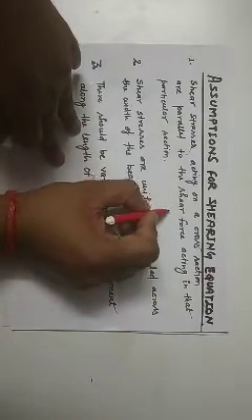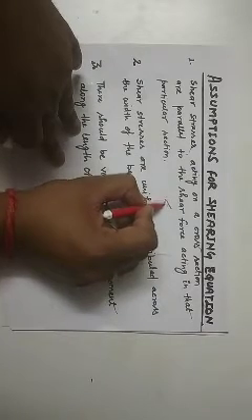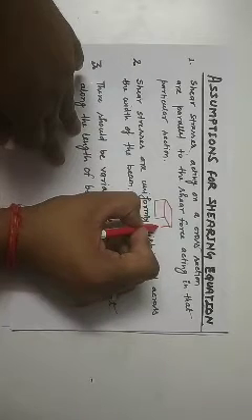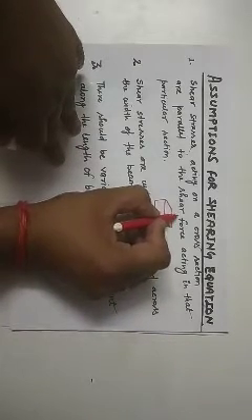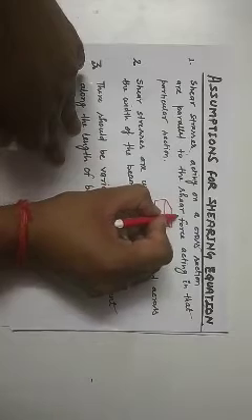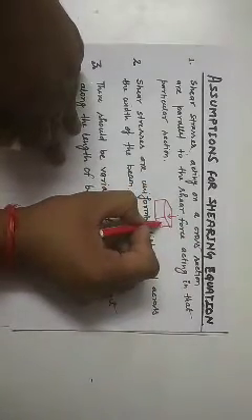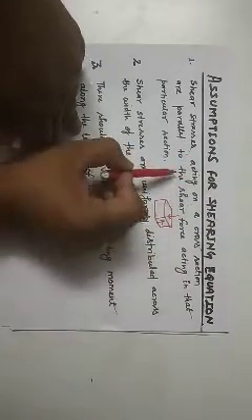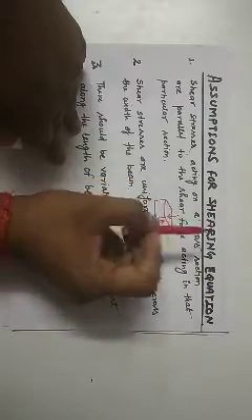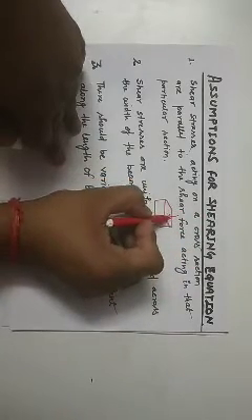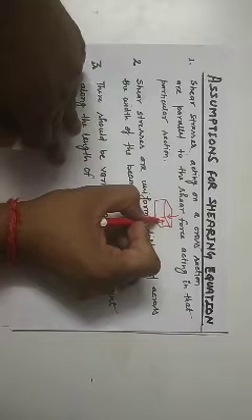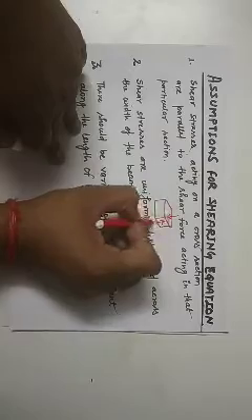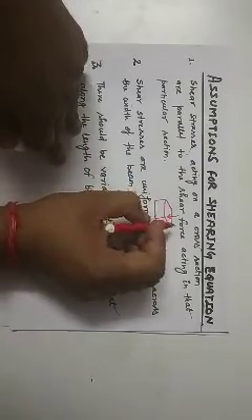If we make a 3D element of the beam, then stress, shear force, load always act normal to the surface. Then the shear stress that is generated will be along the cross section. This is written here: shear stress acting on a cross section is parallel to the shear force acting in that particular section, right? So these forces are along the cross section, they will create a shear force in this direction. In the same way, along these lines, shear stresses will be generated in the beam.